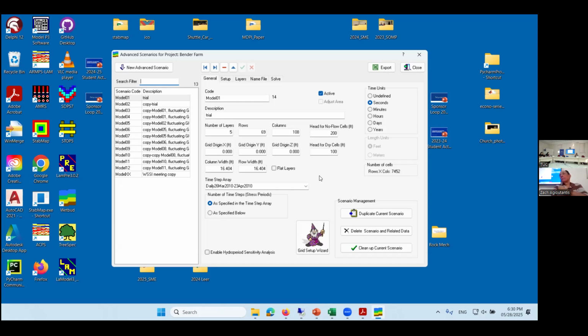To come back to my previous question, about this specific tool, if we can transform an existing pond or lake to a wetland, there are some options for big lakes that are created in mining areas. Instead of it just being a lake, if there is a nearby river, you can create a channel that you connect, you can feed the big lake, and you create an outlet as well. And then you can plant things in there to clean it up. It's exactly a reclamation area and a reclamation plan for a waste-to-waste solution. Very good. It's something that we also see in different projects, and it's a good option. And you can have a design tool to see, according to the hydrological conditions of the area, if this is possible, because sometimes it's not, if we don't have the right hydrological conditions.